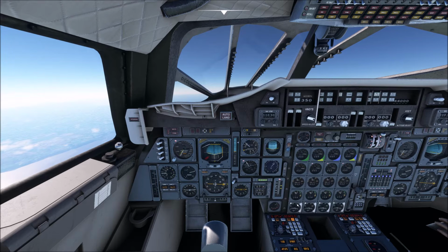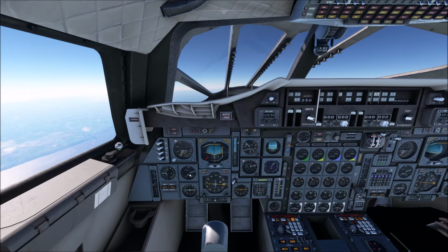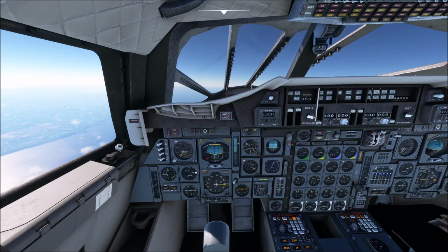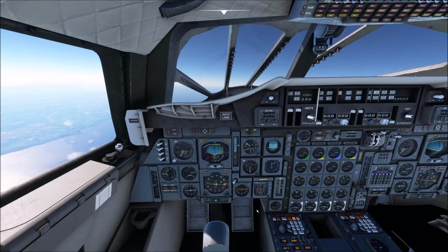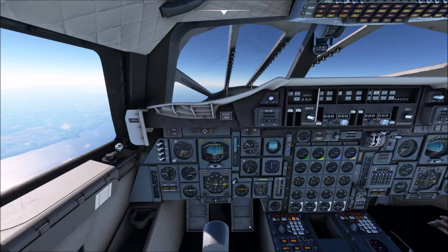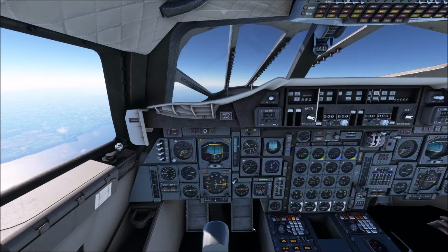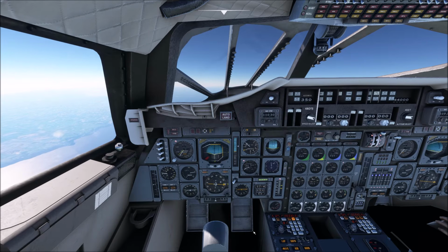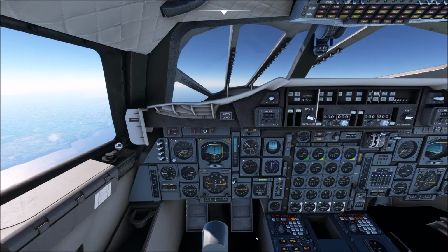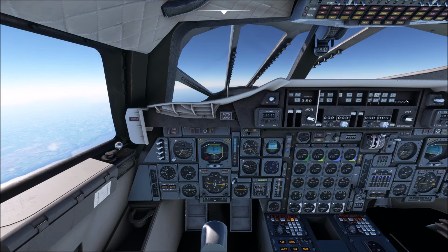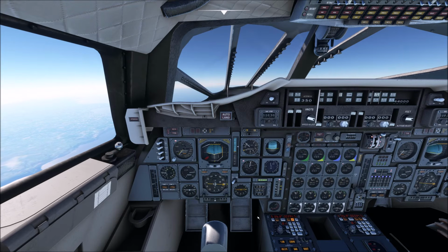And this is the reason we have the afterburners on here, is because this is what's called the high drag area of the flight regime. Concorde has to push through from here to Mach 1.7 and flight level 440. Once it achieves that, it will no longer need afterburner. It will be going fast enough and the aerodynamics will be working in the correct way, and it will mean that the aircraft can then stop using afterburner. So you level out at 440, turn off the afterburner switches, the reheat switches, and thereafter it will climb just using dry power, but obviously at a much reduced rate because of the much reduced thrust.